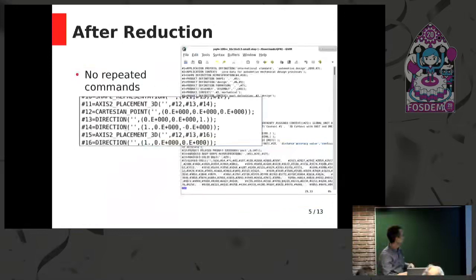And how do you do that? Well, you step through and you can either parse out the individual elements, in which case you have to recognize there are in the step format, trying to remember the exact number, I believe it's about 400 different commands. So you could parse those 400 different commands and figure out how you do that reference, or you do something a little bit safer and perhaps more naive, which is what I chose to do here, and you do a string comparison.